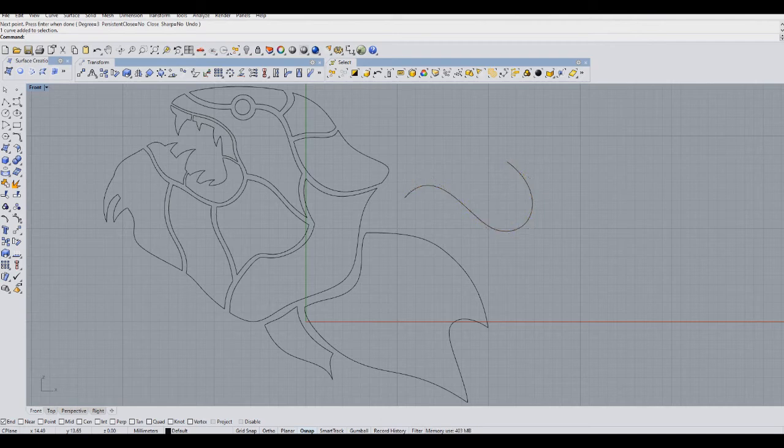In the past, when you had a curve and you wanted to manipulate it in some fashion with the control points, after putting it down, you'd have to select it, and then you have to hit Show Object Control Points. You could still do that manually, but with the version of the software in 6, now all you have to do is click on it and it gives you those control points, and you can do things like stretch and pull and manipulate the curve to your liking without having to use a separate command in order to do so.